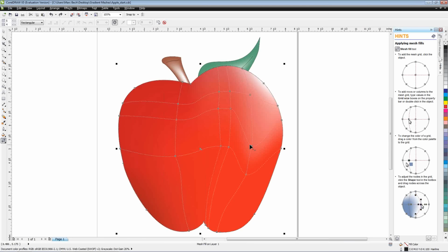Okay, let's now add some finer color points. So I'm going to use selection tools to select the nodes, and then with 2 white nodes and 2 outer ones. So I'm going to select this node, use the Shift key and select this node, and I'm going to choose white. And then what I would like to do is return these to red. So I'm going to grab that freehand selection tool again and make sure these are all representative of red. And click the red, like so.